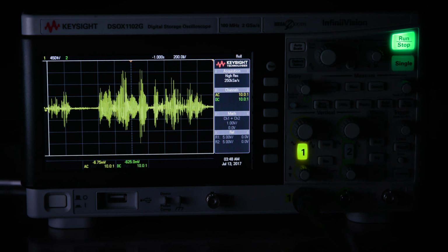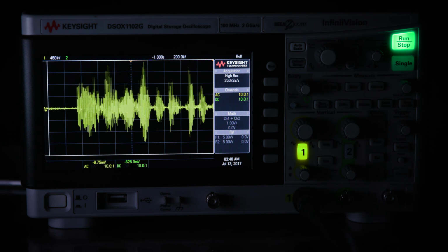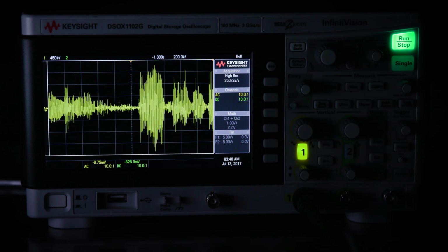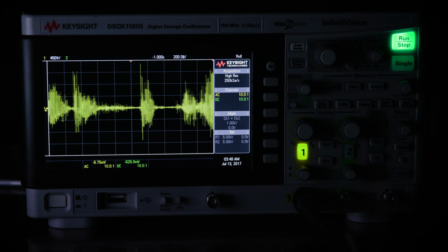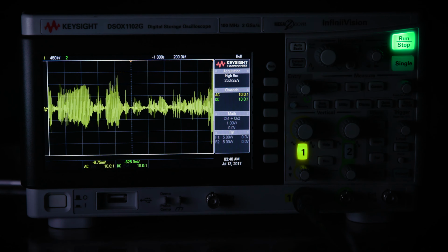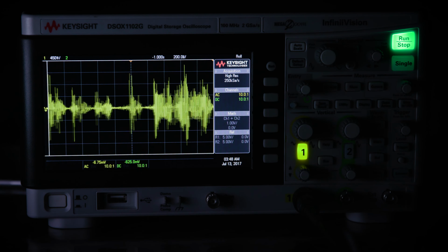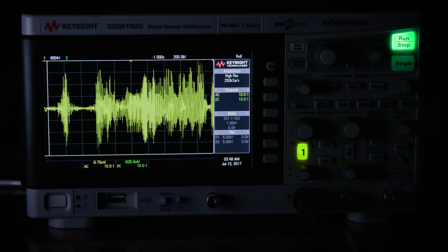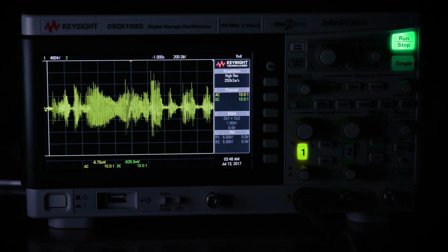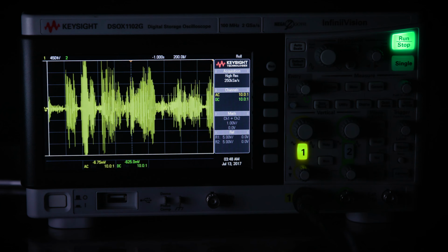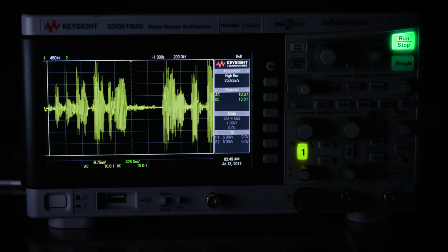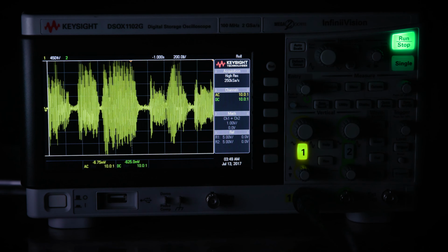You'll get a fixed frequency spur even with no signal in, just the offset. But beyond that, once you start putting signals in, you get what we call gain spurs as well, where you put one frequency in and you get multiple frequencies all across the screen. It's true of all interleaved AD converters, but we try to minimize that as much as possible, and that can be done with analog calibrations, with DACs, with adjusting things. There's also some DSP we can do to remove some of that after the fact.